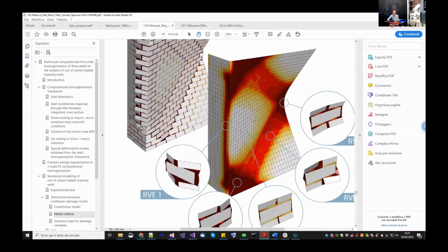And so when you apply the uniform strain coming from this homogeneous model, this continuum strain will be applied on the boundary in such a way that the volume average of the strain is equal over the RVE. And so the output stress will be integrated over the RVE and will be the homogenized stress, okay?